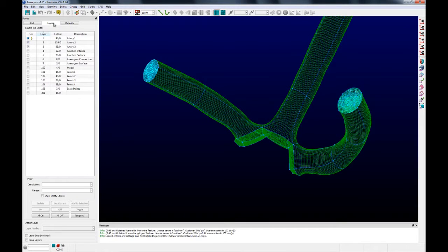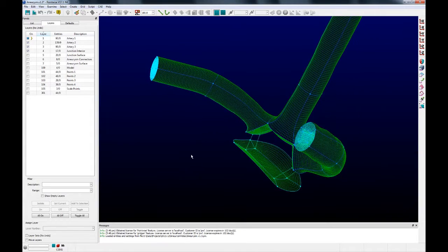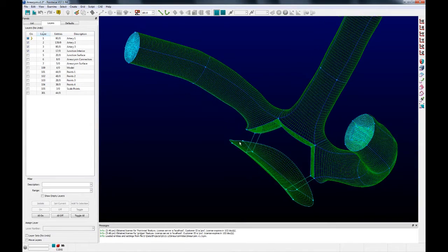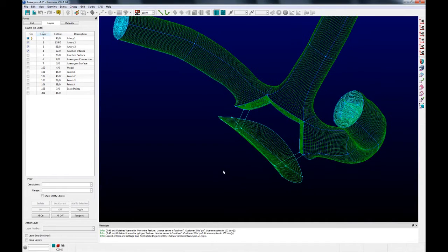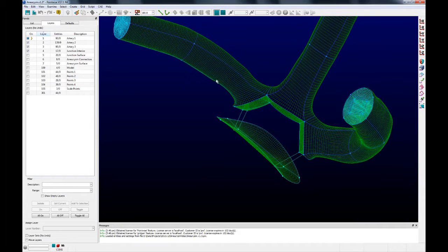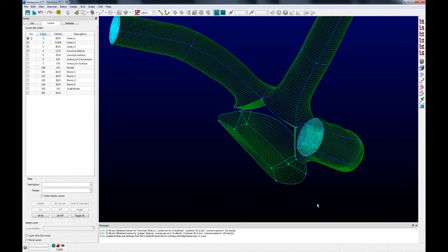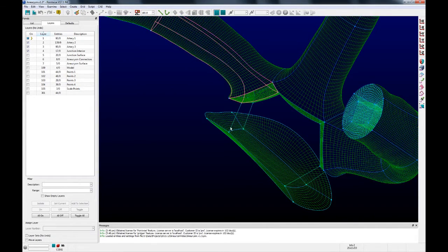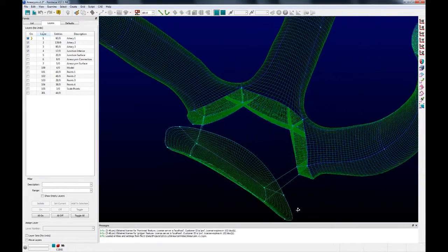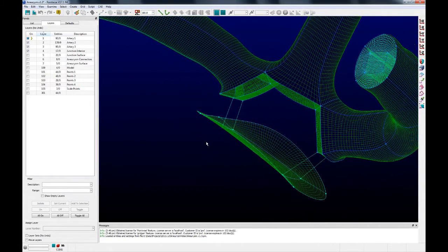So I'm going to hop over to the Layers tab and pull up the junction topology that I've already created. Now, I created this outer topology the exact same way as I created the arteries, I apologize. The curves were initially just placed on the database, much in the same way as I created those curves for the artery. I then created an OH topology with that script, and then I came in and manually drew some 2-point connectors here to connect up this topology. Otherwise, it's exactly the same process.